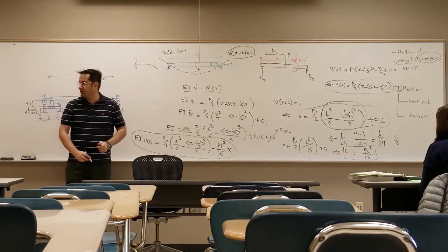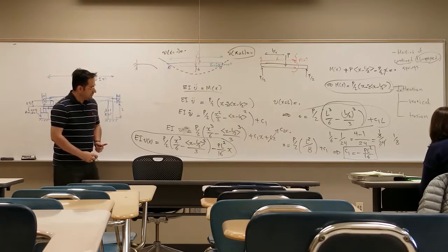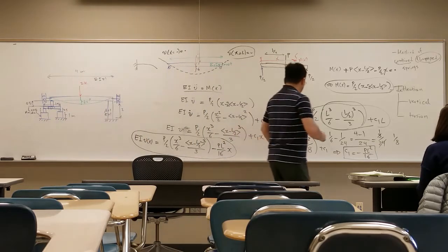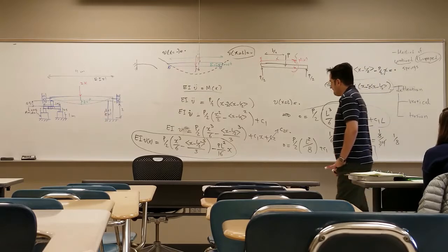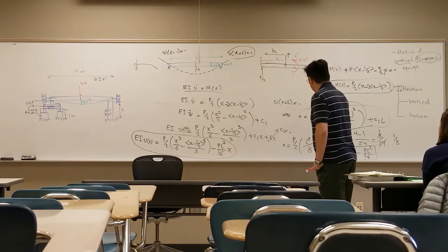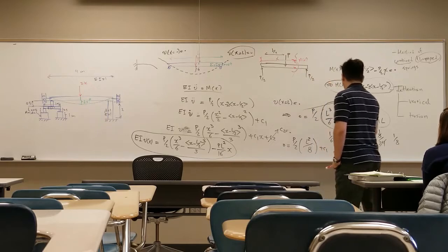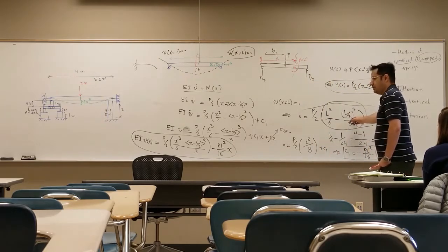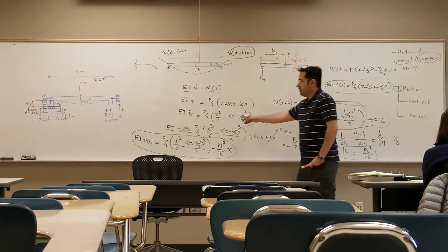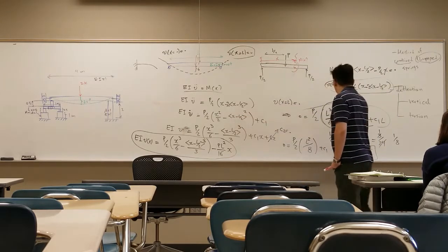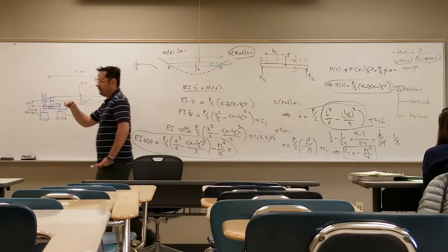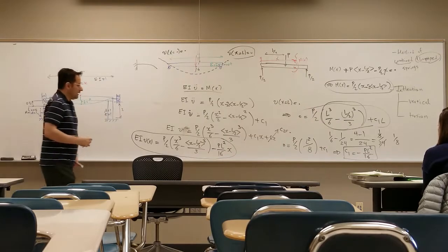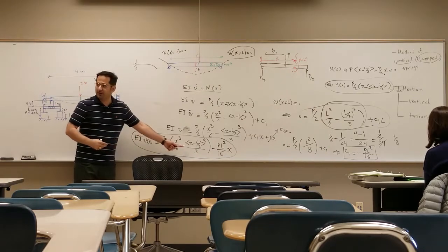What happens to the other L? In your equation, I'm sure that you circled where you put the L's in the spots. Which one are you talking about? This one? Yeah, you have Heaviside x minus L over 2. Shouldn't it be L minus L over 2 when you plug it in? Show me exactly what it is. You're talking about this guy? Yeah, L minus L over 2 is L over 2. Okay, there you go. It is possible that I'll make a mistake in this calculation, so it's good that I always verify what I'm doing here. So you get this equation for the elastic line, right?